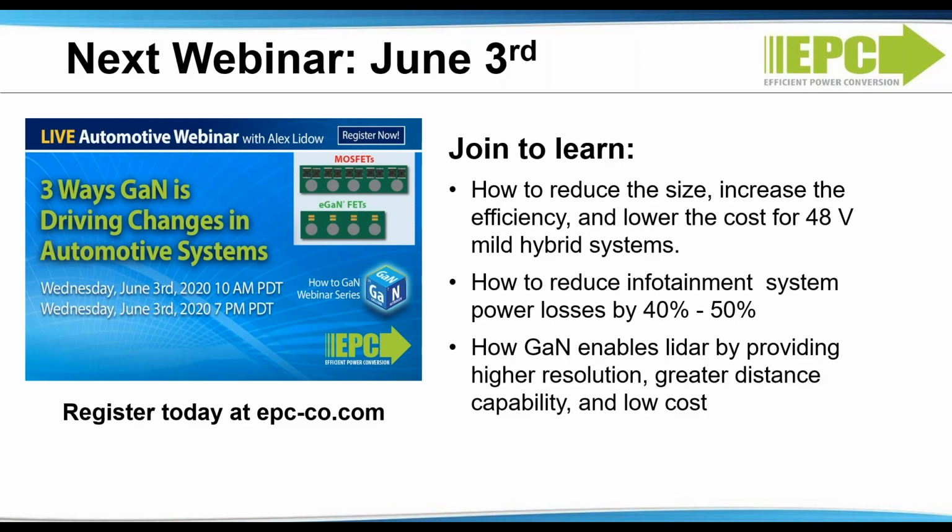For the 48 to 20 volt converter, the largest losses again come from the inductor, and I think that's probably the biggest one in general. Okay. How does the RDS(on) of GaN change with temperature increase? It's about the same as a silicon MOSFET. Between 25 and 125 C, the on resistance will increase about 1.6x.